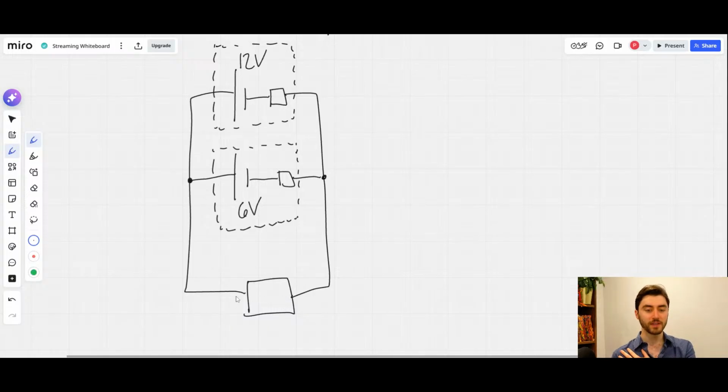So there is a fixed potential difference across the resistor, which means there's a fixed potential difference across these points, which will be the same in both branches of the parallel circuit. Which means my claim is that V is the same, even though epsilon is not the same, because V is equal to epsilon minus IR.